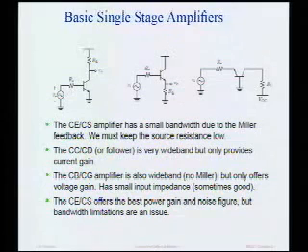That means it's going to produce a low-pass filter at the input of the amplifier. Depending on the source resistance, if you're voltage driving this amplifier, that might not be a problem, but usually you're driving it with some source impedance. Source impedance might be your cable characteristic impedance. That's going to produce bandwidth reduction. So that's the problem with a common source amplifier, and we can solve it by operating with low source impedances. In a lot of communication systems, that's pretty easy to do because we have low impedances. Cable impedance might be 50 ohms or 75 ohms.